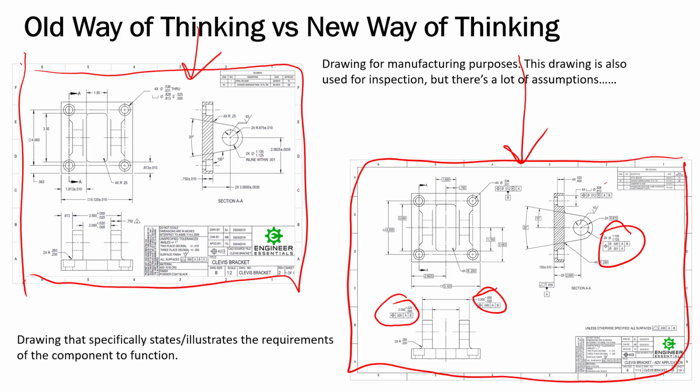And all of these have an A and B reference, so it's back to that bottom plane and then the bolt pattern. If we come back over here and look at the coordinate dimension print, most of them are coming from this bottom over here, but now look over here, we're coming from the side. So these are all coming from this one side over here. Again, like I said, the outside serves zero purpose, and that's what this drawing over here is showing.